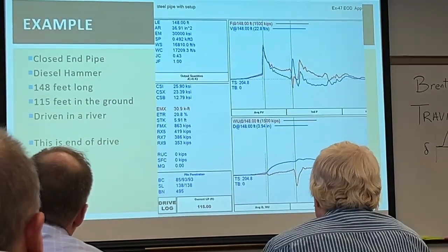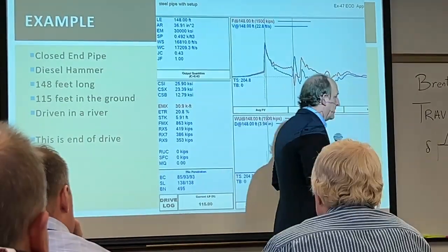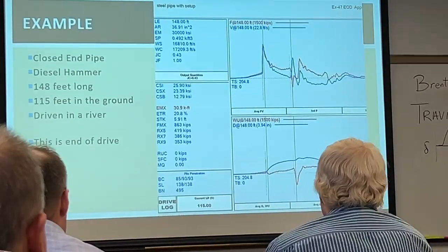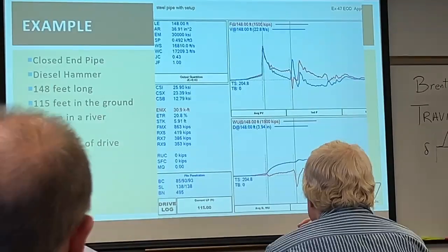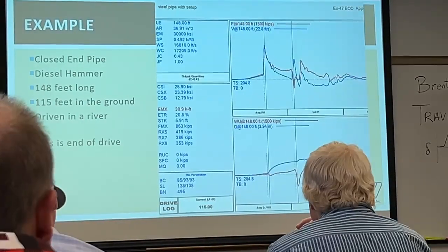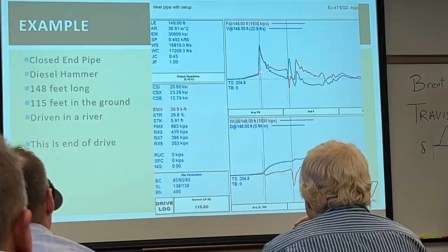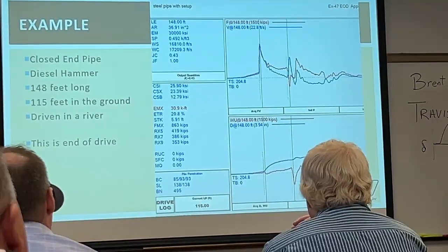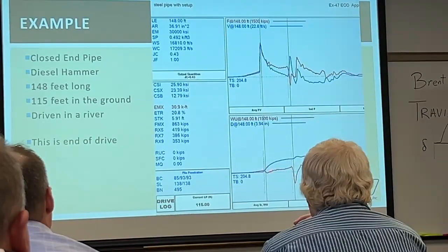So knowing what we now know, is it a diesel hammer? Yes, I said it right there. But we can also see the pre-compression. How's proportionality? Very nice. Any shaft resistance? Yes, and we can see that in our wave up curve as well.